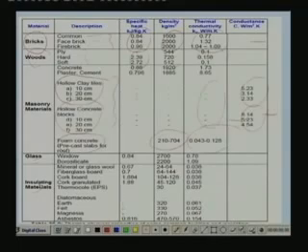These kinds of properties are available in air conditioning design data books such as ASHRAE data books or other air conditioning books. Looking at the tables, you can take the properties like specific heat, density, thermal conductivity or conductance. If you are calculating the overall heat transfer coefficient, you can use either the conductance value or the thermal conductivity and thickness, and you can find the overall heat transfer coefficient. From the overall heat transfer coefficient and the temperature difference, you can find the heat flux through the wall.